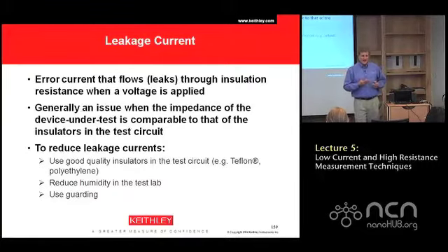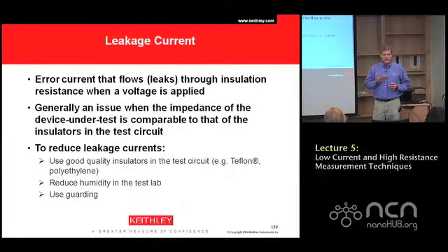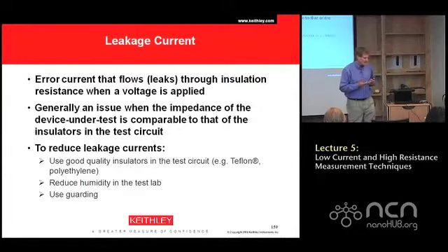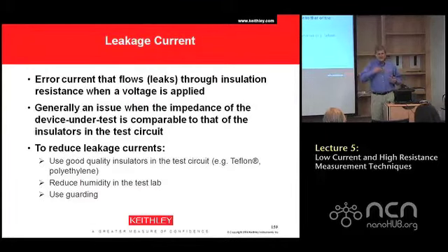So the conversation that we had at lunch when we were talking about measuring the voltages on nerve endings, okay? Well, that's a particularly difficult thing to do because the nerve ending is a relatively high impedance device. That means the sampling head, whatever the sampling head is, has to also be a very high impedance device, or it will simply discharge the nerve ending and none of the signal will get out where we can measure it. So the impedance of our device and the impedance of our cables and the impedance of our instrument, it's important to be aware of all that, particularly when impedances get high.